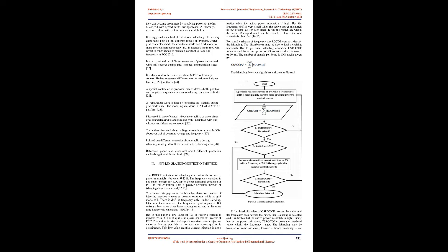If this small percentage is not enough, it is slightly increased to detect actual islanding. Hence the zero active power mismatch case is also handled to detect islanding, by shedding the local load and bringing the load frequency to 50 Hz [8, 9].